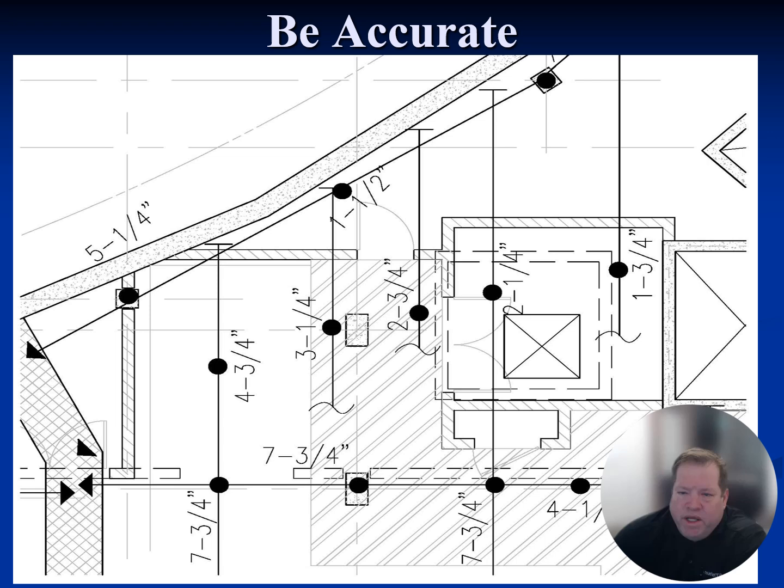15, 17, 20, 25, 30 feet. If the 14 by 22 works for 30 feet, it's going to work for all those conditions. No one's going to ask you for calculations and all that kind of stuff. By default, we all get that. Again, it's passive reinforcement.